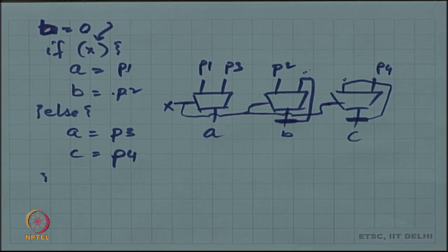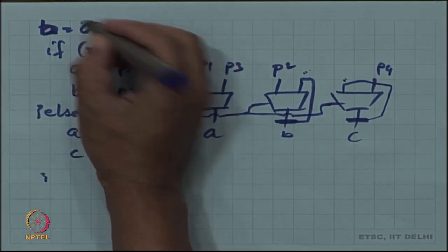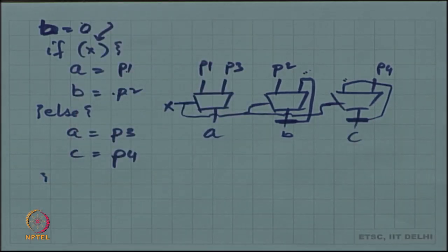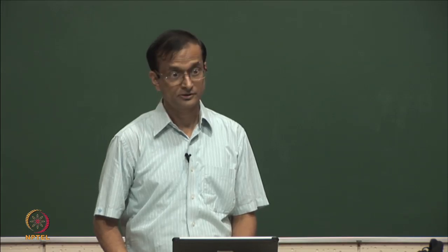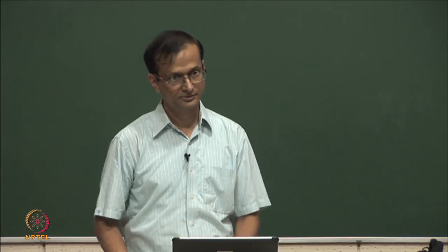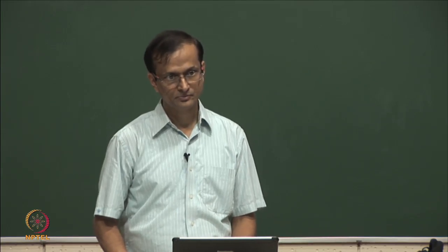So, then we could just have whatever that value was, we could add it to the mux, and that may help us avoid the latch in the general case. So generally the tools don't allow the use of if without a process. If these are statements that would go inside a process, yes. The if statement is there only inside a process. So that default value that you are saying, it should be assigned outside the if, within the process, but outside the if. Right. Okay.